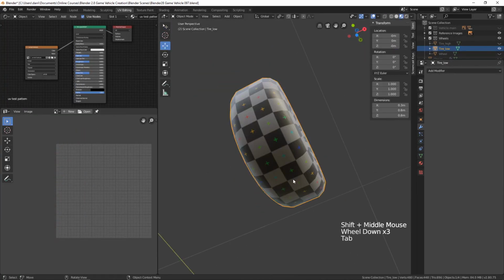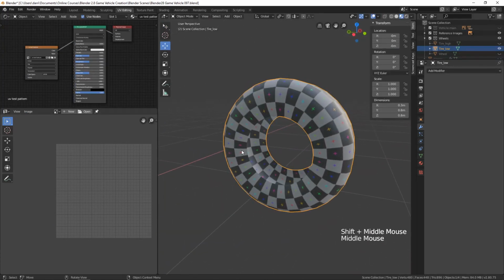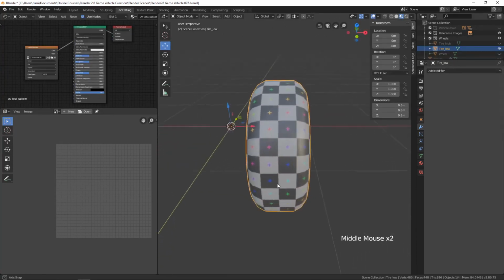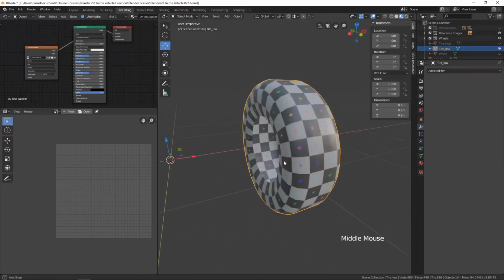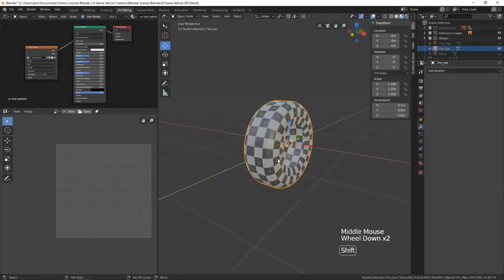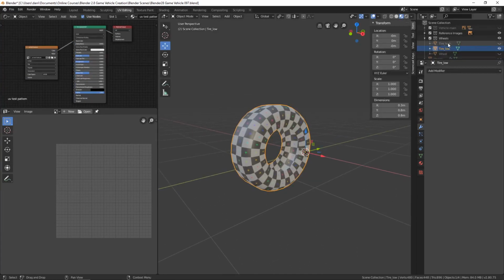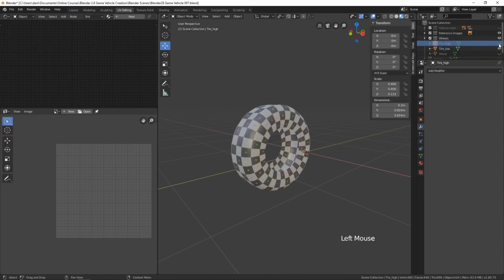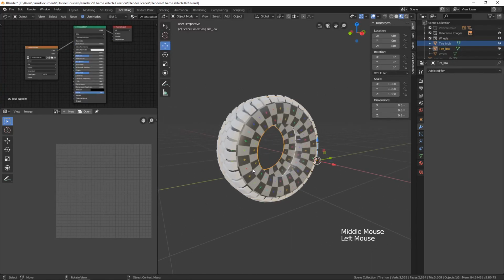So now let's take a look at these. These look a little bit better. They're still going to be a little squished here on the sides, but our main concern is up here where the treads are. And those look pretty good. So, what have we done here? Why have we done this? Well, we're going to take this and apply the high poly information here. I'll unhide that right here. We're going to apply this high poly information, all this detail, to the low poly object in a normal map. And I'd like to do that in Substance Painter.